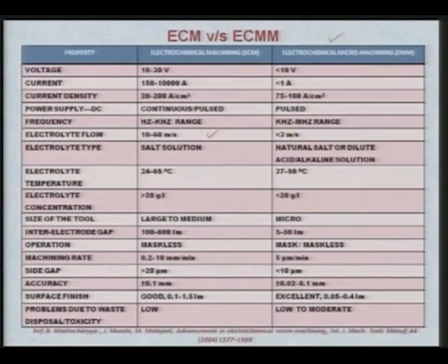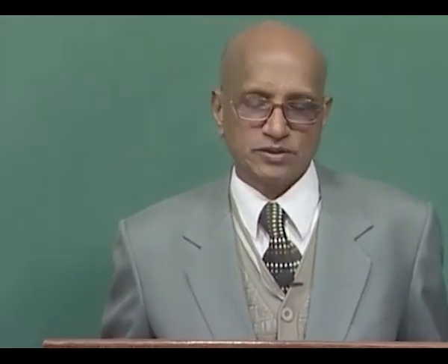You can use various kinds of electrolyte in both cases. Electrolyte temperature does not go very high in both cases, normally within 60-65 degree centigrade. However, theoretically you can go as high as 90-95 degree centigrade, below the boiling temperature of the solvent, that is water in normal cases.